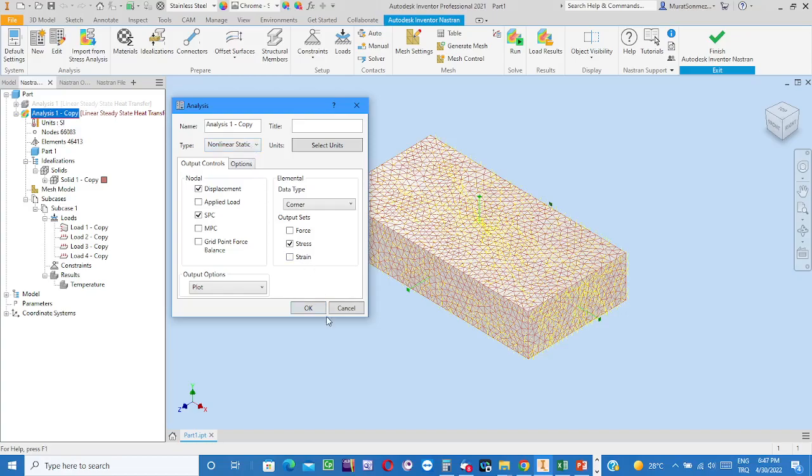And then, when you finish the running, do you want to see the results? Force, strain, stress. Well, we wonder about the stress value. So for the stress output set, select stress. But you know, after having the scale in the vicinity of the model of the object, then drop a list and select not stress but force, not force but strain, not strain but factor of safety.